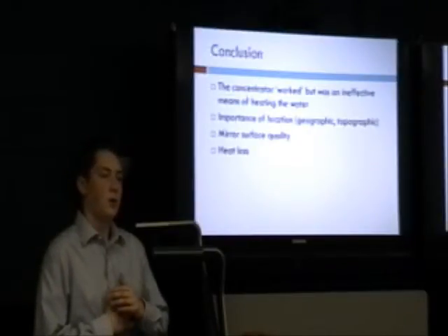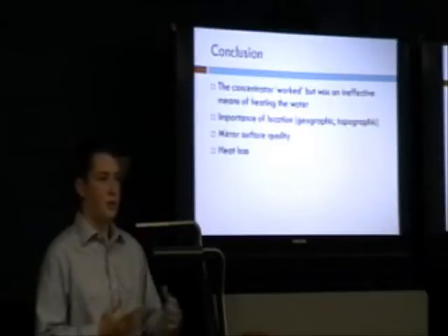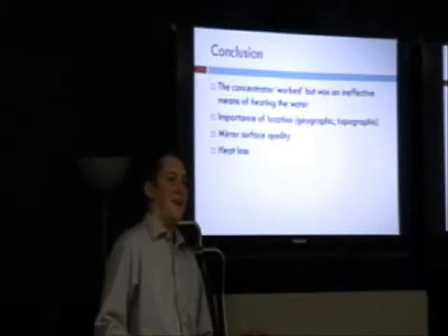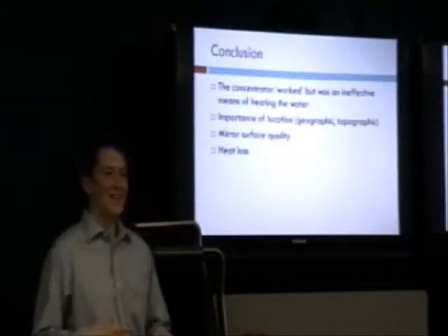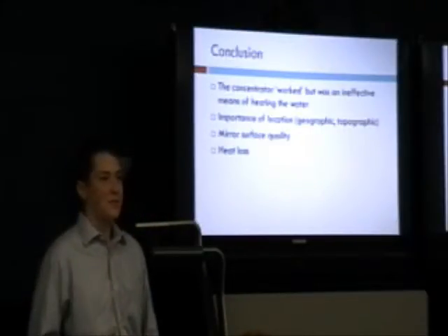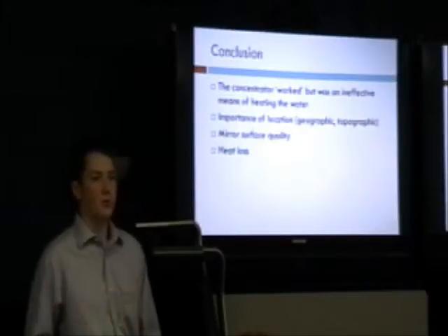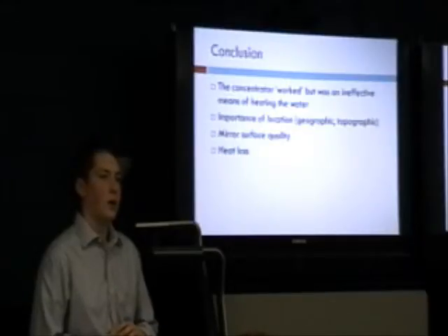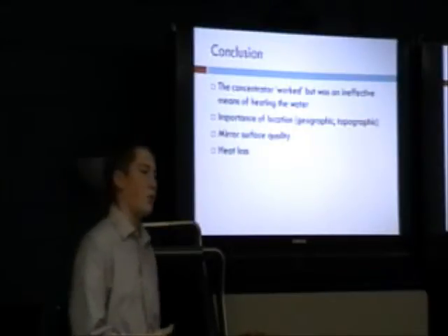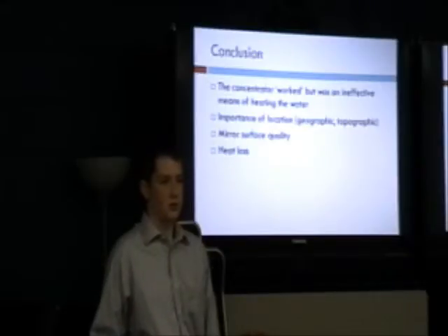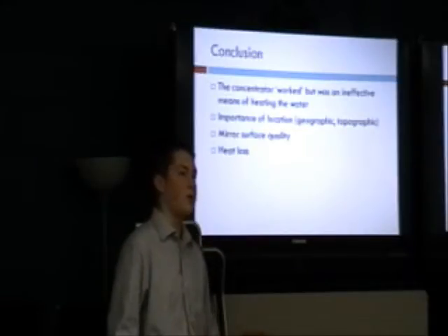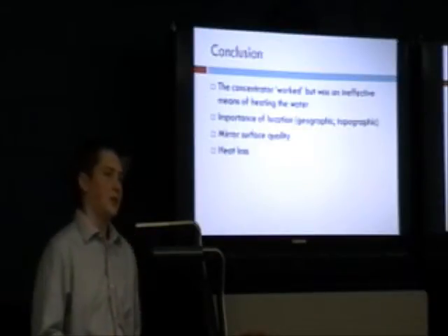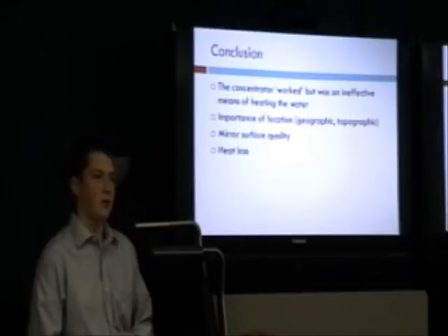Mirror surface quality, especially, again, built near the tree line, a lot of issues with wildlife and trees, pollen, that kind of thing. You don't really think about this, but the mirror surface will degrade after it sits out there for a long period of time. And this is also an important issue with commercial applications, especially in hot, arid areas where you have to clean the dishes. It's a huge water use issue in these hot areas. And here, not an ideal place, where you have the pollen on the dish, that kind of thing.